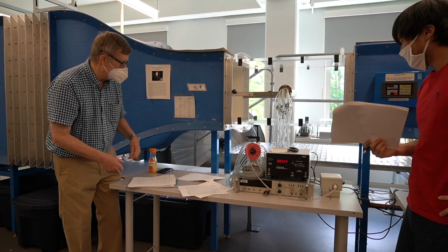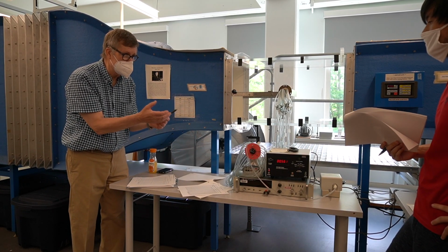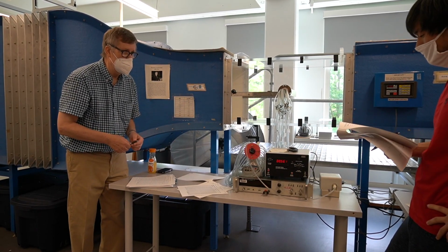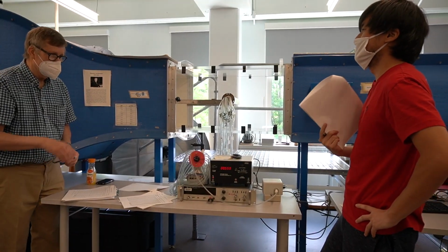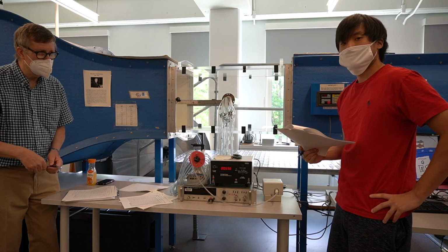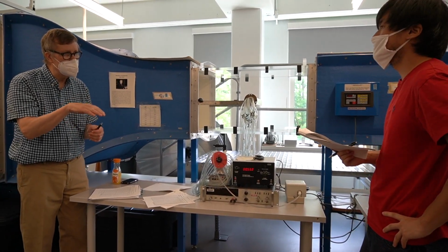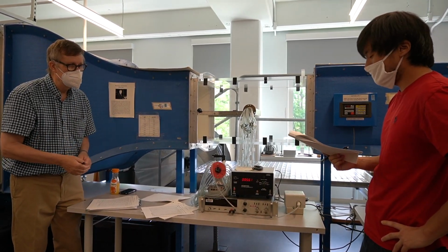So basically, if you have a stagnation point, PT minus PS measures the pressure difference at the stagnation point. What does that tell us about where we are in the flow on the cylinder? We're dead middle, in the center. So it's another stagnation point. It's not exactly a stagnation point because it doesn't move up and down; that's to do with the vortices forming behind the body.